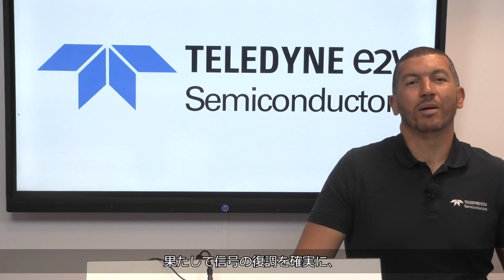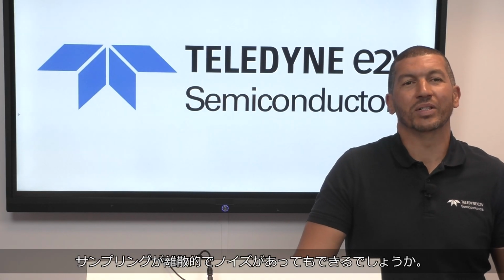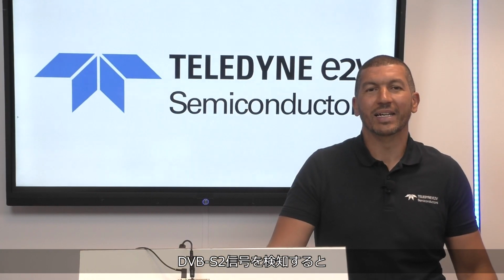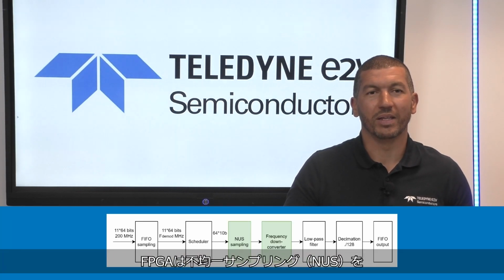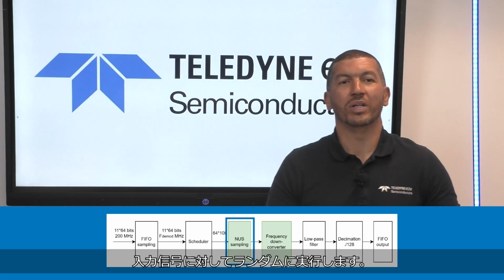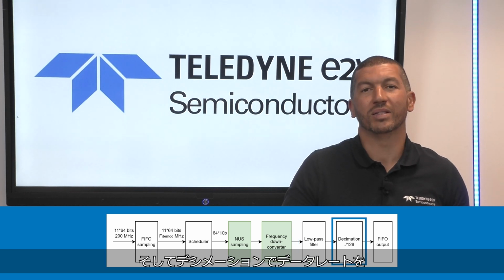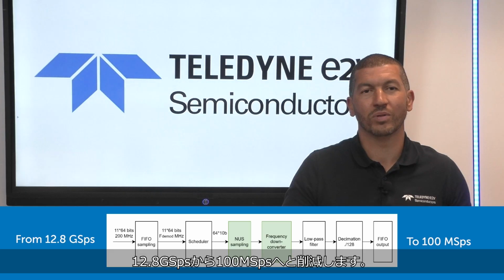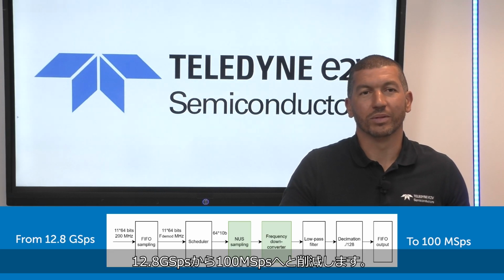Can we reliably demodulate signals even when sampling is sparse and noisy? Once a DVB-S2 signal is detected, it is demodulated through a hybrid pipeline. The FPGA performs random non-uniform sampling on the input signal, frequency down conversion, low-pass filtering, and decimation, reducing the data rate from 12.8 gigasamples to 100 megasamples per second.